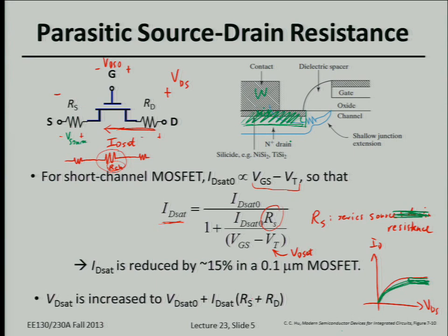Okay. So what happens to the gradient of minority carriers? It gets steeper, right? The concentration profile of excess minority carriers in a short diode region gets steeper if you make the diode shorter and shorter. So that means the diffusion current is increasing, right? Basically, that's one reason why we have to be very careful, especially in this region here.